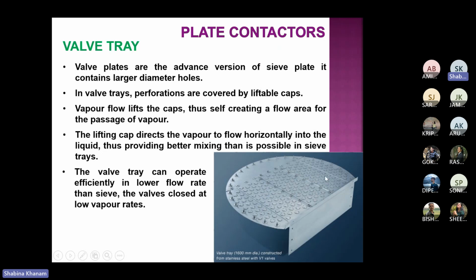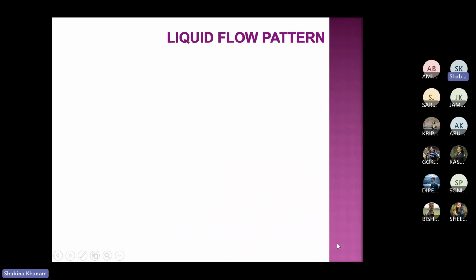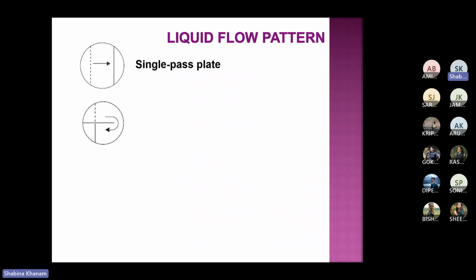This is called the single flow or single pattern of liquid movement. It drops down here, moves over here, exits from here. Simple. That type of pattern we call single pass pattern, or single pass plate. Normally we consider single pass. Next we have the reverse flow plate.